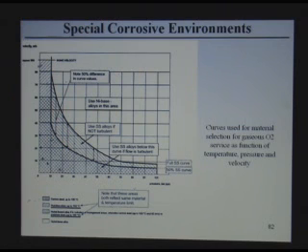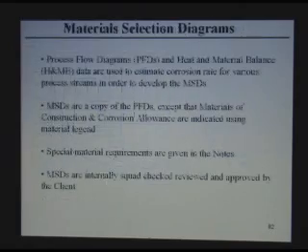Nickel is known to be resistant to gaseous oxygen. And Monel is a very famous material to use in gaseous oxygen to avoid burning. It doesn't burn in oxygen. So this is a curve that we use to select materials. For piping and valves, we use nickel trim, Monel trim, for this purpose, because in the trim you have turbulence, and if you don't use Monel, you might start igniting the trim, and this will ignite the whole thing.